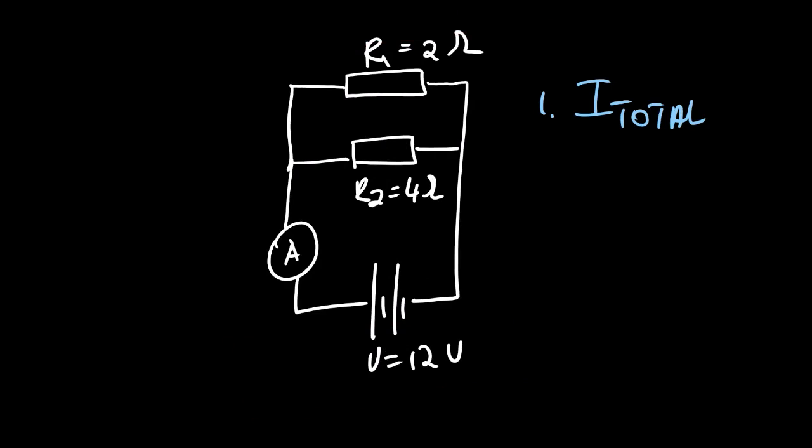Our next question is about a parallel connection. Now looking at this, you can see that it's a bit different from the questions we looked at previously. Now this one, we say it's a parallel connection. Consists of 2 resistors, 2 ohms and 4 ohms. The total voltage is 12 volts. Then the question says calculate the total current. We are actually looking for the reading on the ammeter.